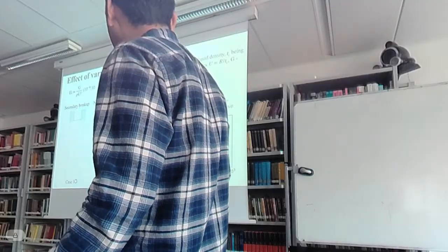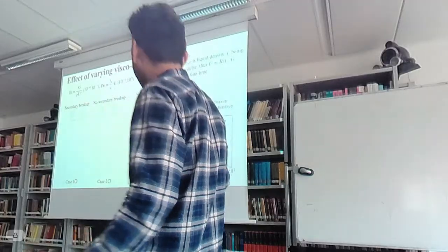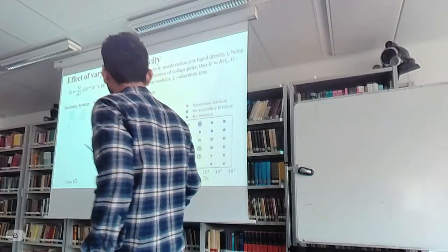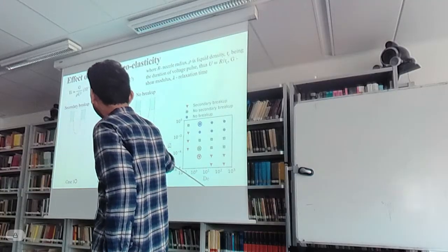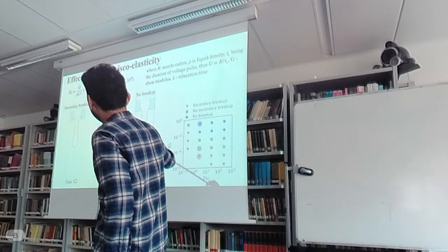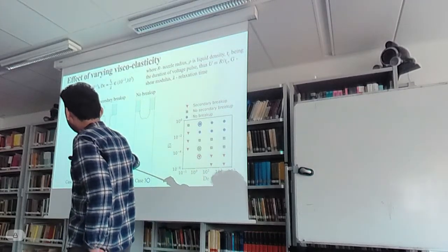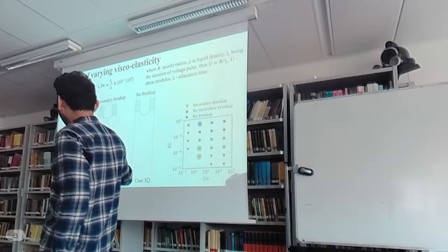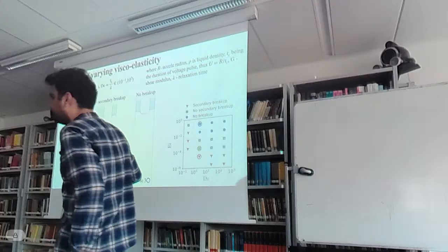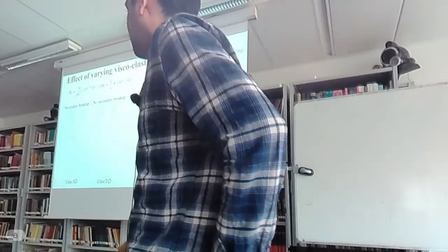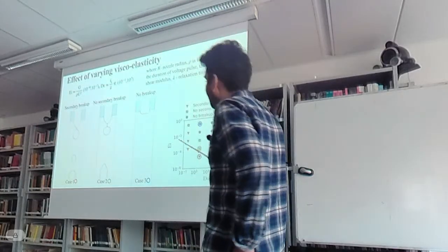And if I do so, I can basically reproduce what we see in the experiments, that in a certain regime you have the jet that elongates, but it doesn't break up, but it retracts back into the nozzle. Whereas in some cases you have a drop which remains attached to the tail droplet, so that you suppress the secondary breakup, whereas here you have multiple droplets and you could not suppress the secondary breakup.